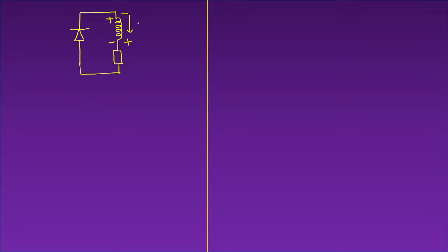But for the inductor, the direction of the current will not get reversed. For the capacitor, the polarity of the voltage will not get reversed. That is the basic property. So this inductor current will remain in the same direction. It tries to come this way, but it can't go through the upper path because there we have an open circuit, so current will not come from there. According to KCL, if the incoming current from there is 0, then the outgoing current must also be 0. So this current will not go in that direction; it will travel through here. That is the first conclusion.